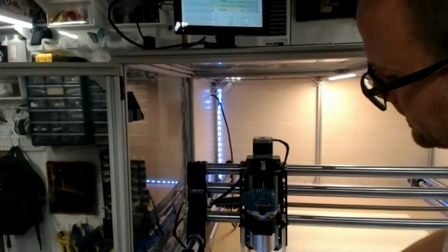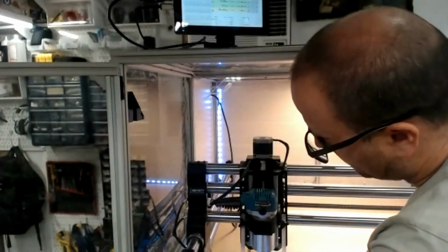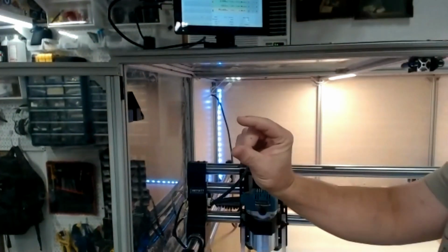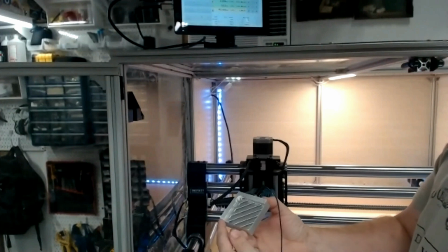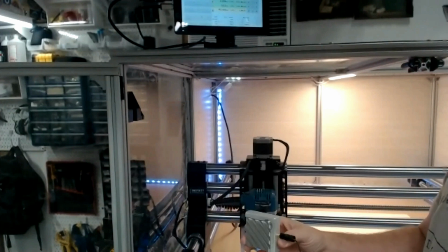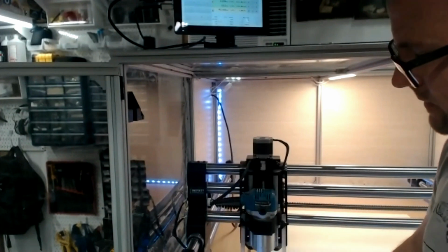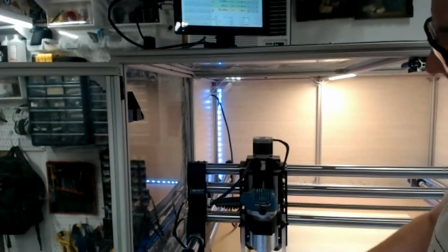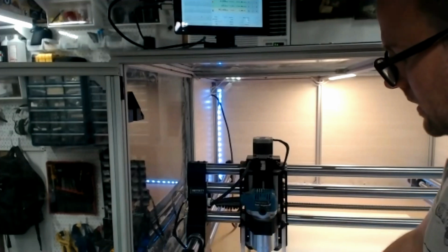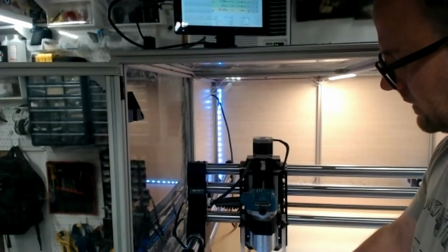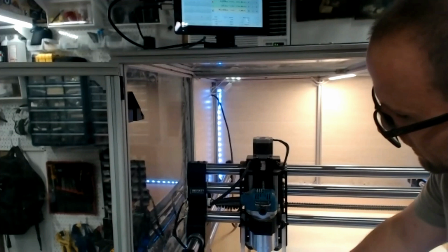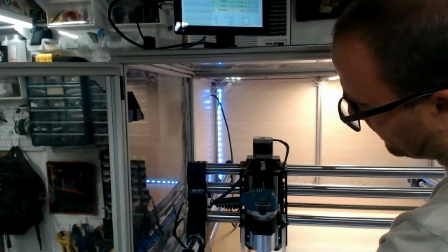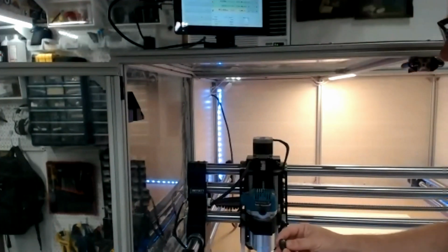So I'm going to slide this up into that notch. Of course, if your material is thinner than that gap, like if your material is thinner than this lip, then you can't use the probe for X and Y because it would assume the probe height instead of the actual piece of the wood. But this is 1/8 inch and it fits fine. So you put your material on and you shove it all the way in the corner, and then you make sure, and I've done this a billion times.